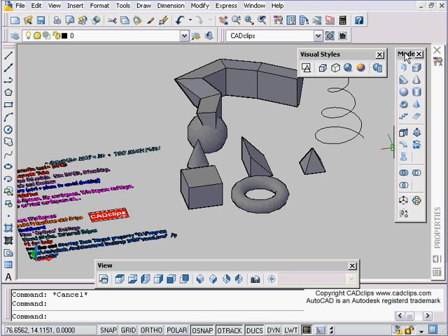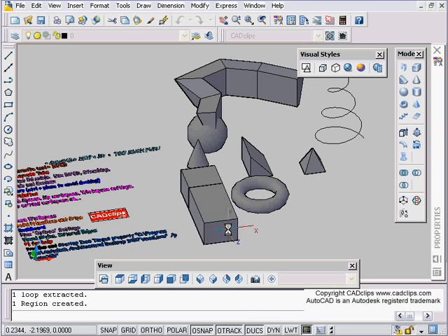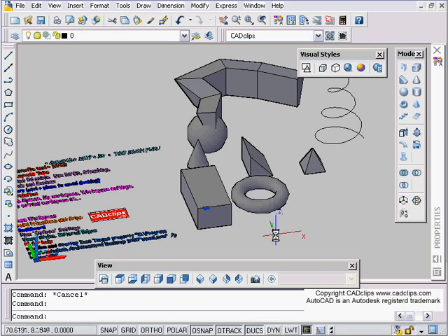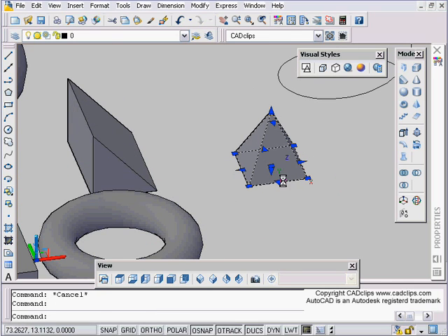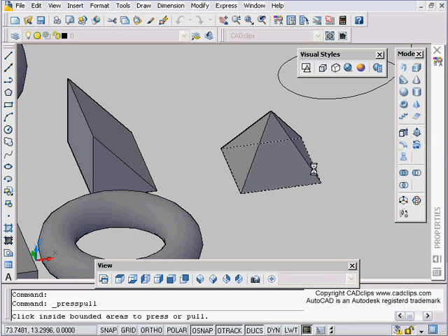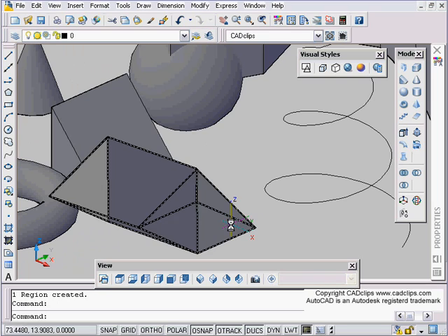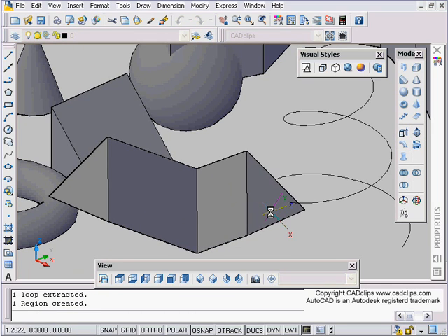Again, this is the modeling toolbar. Right click, modeling. We're going to get into some more of these with our extrude and push pull and stuff like that, where you can go in and pull faces off and all kinds of great stuff. Push, pull, pick on here, pull that face out. Once you've done that push pull, you'll notice you'll lose your grips. I can go down to here and pick on this object, and I can grip it and do all kinds of great stuff with it. Once I go in here and use my push pull, pick that face, I can pull that face off, which is really nice. Same as I can go over to here, pull this face off.